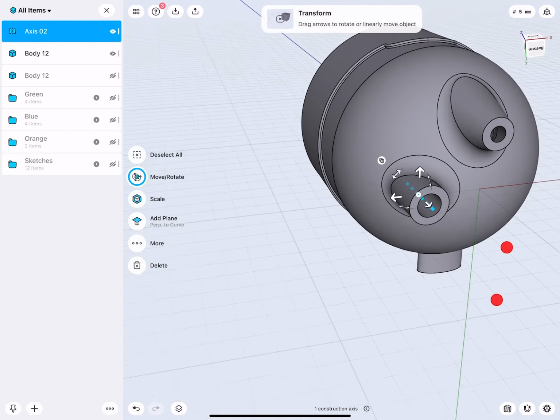And this line, let me delete this. I just drew it between this control point and this line. I make them tangent, or I could also simply make them horizontal there. And when I just move this point, you see this way I make sure that they're horizontal, but I don't really want to change the size here. So I can select these 2 points and then move them. And you see now how I'm just moving these 2 points, and the rest of my spline on top simply adjusts a little bit.